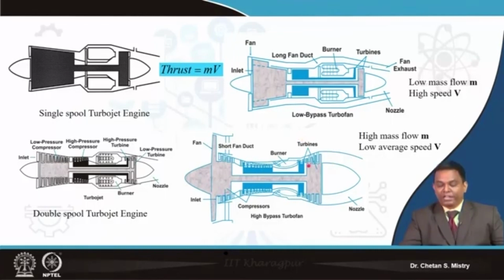We can increase our fuel efficiency by increasing turbine entry temperature, but we have a constraint with heat transfer. In order to address this, we have this big size fan that gives the bypass air which can cool this particular region, and that gives an additional benefit. Let me tell you, this high bypass ratio engine gives approximately 70% of your thrust, and that's a major choice.